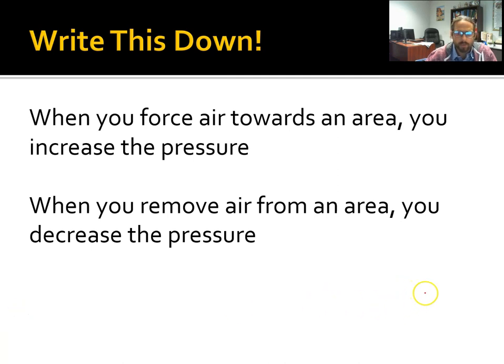Okay? And I'm going to give you a quick example here. I'm going to draw this with my mouse, so excuse me. But if I have a wall and the floor, and I have a little space heater in the corner, what's happening with this space heater is the air around the space heater, here and here and here, is going to rise up. So what that does is that ends up lowering the pressure right next to the space heater.